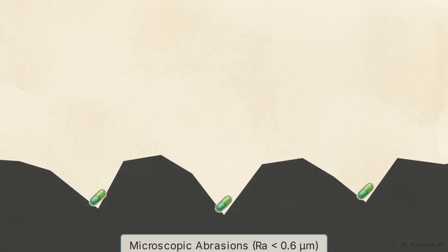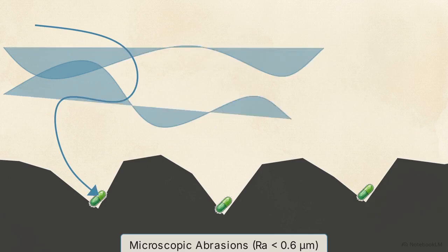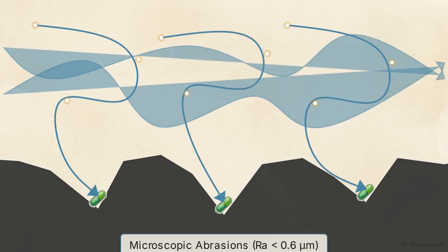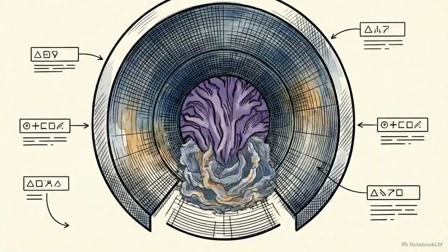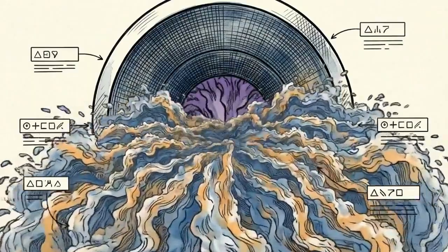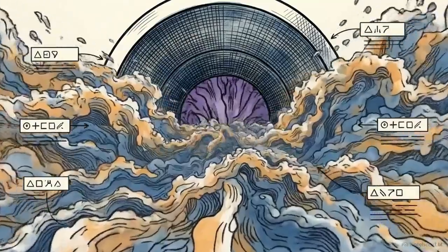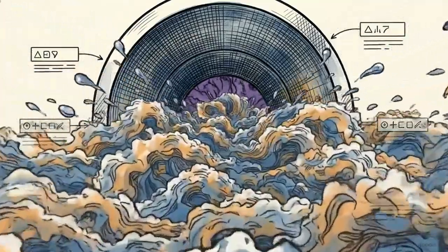The same principle applies to chemical distribution. Even highly polished steel has microscopic abrasions. Turbulent flow physically drives sanitizing particles deep into those tiny crevices, ensuring the chemical agent reaches every biological hiding spot. Increasing water speed is a means to an end. Powerful turbulence is the required delivery mechanism that allows heat and chemical sanitation to effectively sterilize the pipeline.